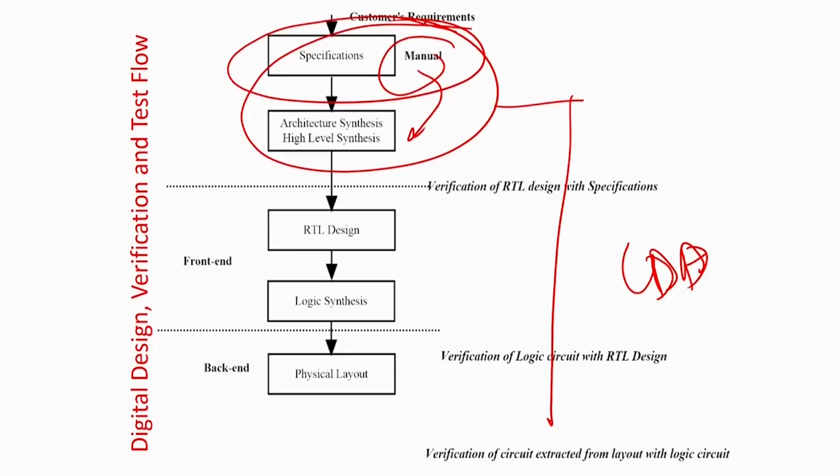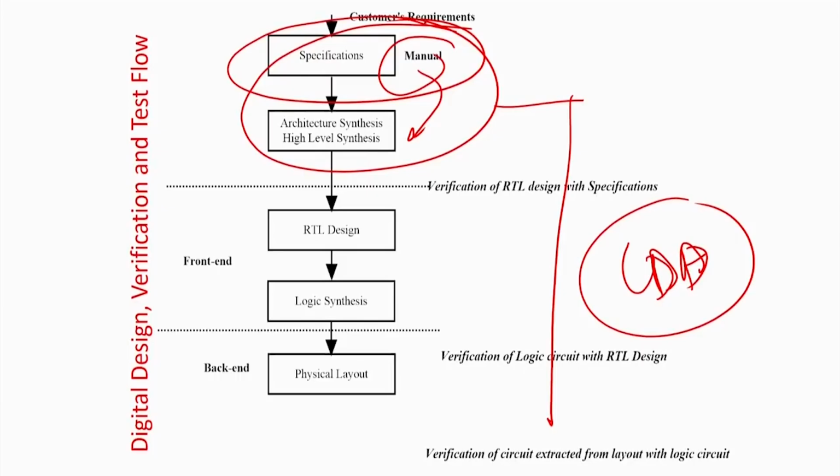Once that is done, more or less all other parts are full of algorithms. Like if I have a Karnaugh map or a Boolean function given to you, how can you implement it in terms of the minimum number of gates? You can use a Karnaugh map, you can use the Quine-McCluskey algorithm, or for example if you want to implement a counter, we know that we have a present state and a next state, then we go for a finite state machine level implementation. But all these things can be written as code. That is nothing but your CAD for VLSI. So there are a lot of CAD tools to solve the problem, but the only thing is that now the number of input variables is not 4 or 5, they are hundreds and thousands. So how to solve it?